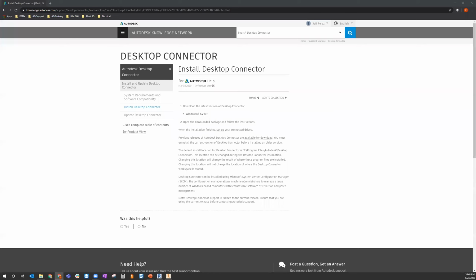So again, I did cover some of this within my previous ABA, but just to recap, within Inventor, when bringing your Inventor models to Revit specifically, what I would do is use a lot of Inventor's shrink wrap functionality to simplify your model, really, is what you want to do. You don't want to be, for instance, maybe you are developing an AC unit. You're not going to want to bring in an AC unit with all the various internals that are required for that AC unit to function.